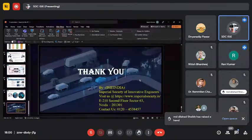Wait, I will explain that. In the BLDC motor, we provide DC power source to the controller first. Then the controller creates a DC pulsating output, which is a trapezoidal waveform, and that power supply is given to the BLDC motor. Simultaneously, the controller supplies the Hall effect sensor, which detects which polarities will change, and according to that, which magnet has to create a north pole or south pole. On that response basis, the BLDC motor works.